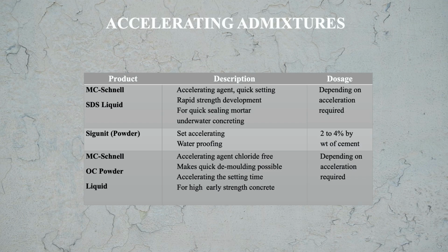Its dosage depends upon the acceleration required, and its characteristics, if we look at, are that it is an accelerating agent, induces quick setting and rapid strength development, and is used for quick sealing mortar and also for underwater concreting.